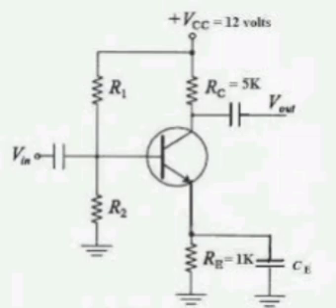In the circuit shown in the figure below, the gate voltage Vg is very small. Assume the op amp is an ideal op amp. Vtn equal to 1 volt and mu n Cox W by L equal to 200 microamperes per V square. Calculate the output voltage. The circuit diagram is this, an N channel MOSFET. The source has minus 2 volts. Drain is connected to the negative terminal of the op amp. Positive terminal is given 4 volts.